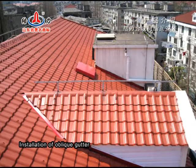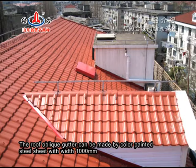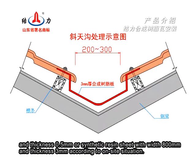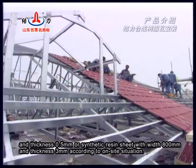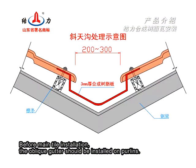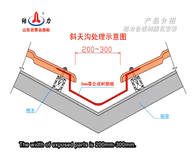Installation of oblique gutter. The roof oblique gutter can be made by color painted steel sheet with width 1000 mm and thickness 0.5 mm or synthetic resin sheet with width 800 mm and thickness 3 mm according to on-site situation. Before main tile installation, the oblique gutter should be installed on purlins. The width of exposed parts is 200 mm to 300 mm.